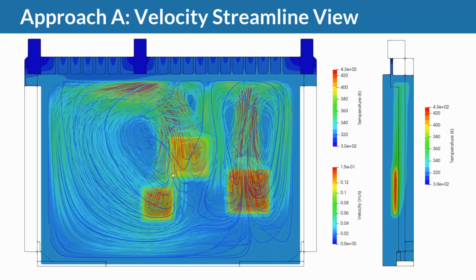So the chips heat up the air in front of them, and it then rises because of buoyancy effects to the top, and up there it transmits the heat to the enclosure. It cools down, and this vortex or air movement inside the enclosure starts happening, right?